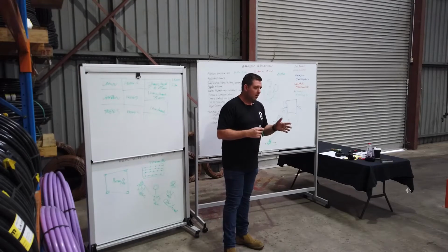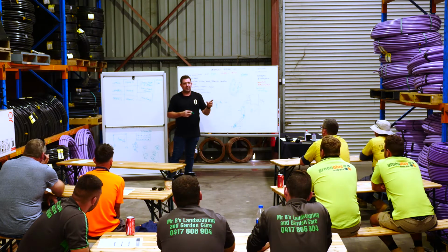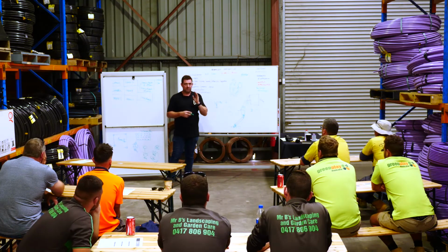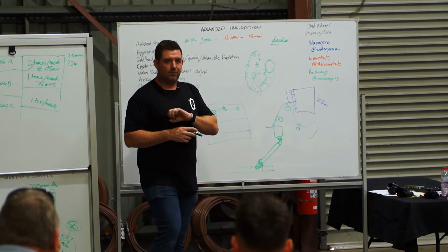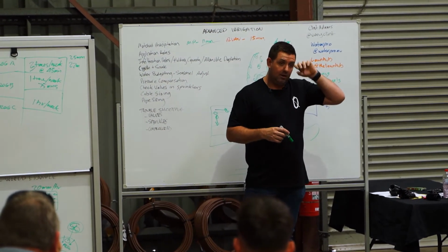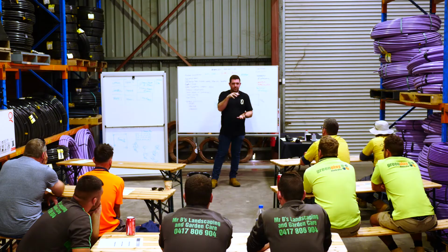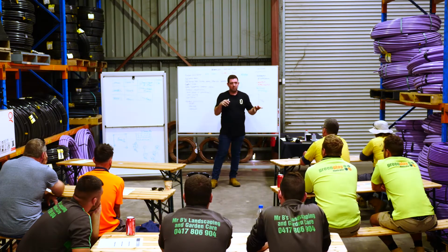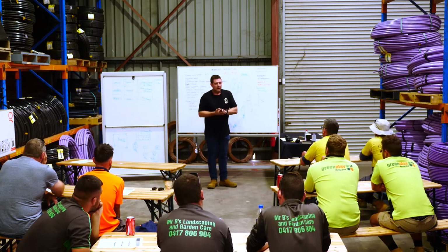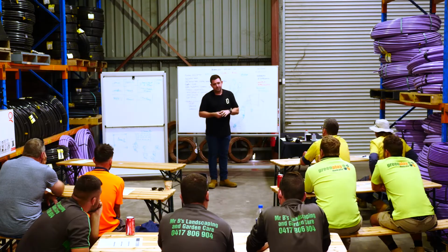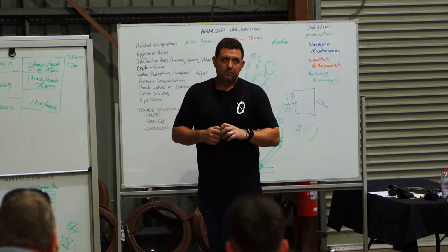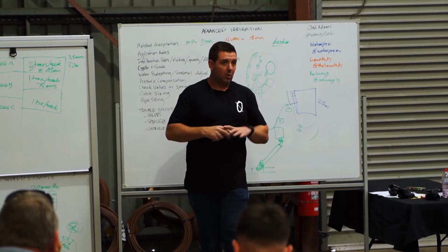So when we design an irrigation system, we try to keep the velocity of the water moving through the pipe below 2 meters per second. If it's going too fast, it'll hammer, and you'll hear the screeching and the hammering. So the way we reduce that is by making the pipe bigger, so that we can get more water, I guess more liters per minute in the time, so lower velocity. I think that's right. If you try to run, say 40 liters a minute through 13 mil, you're going to have trouble. So 25 mil residential is always going to be fine.